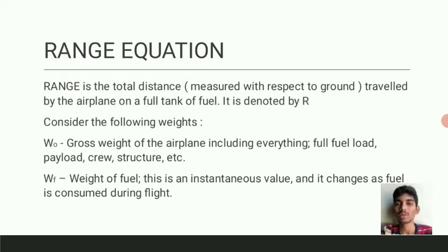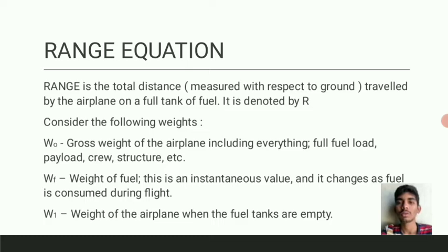As you know, if the plane is moving, it consumes fuel. Therefore, the weight of fuel will vary with the distance. Therefore, WF is said to be an instantaneous value. And next, W1 is defined as the weight of the aeroplane when the fuel tank is empty. If the aeroplane's fuel tank is empty, then the weight we get is known as W1.